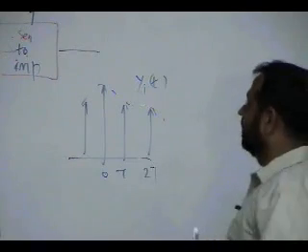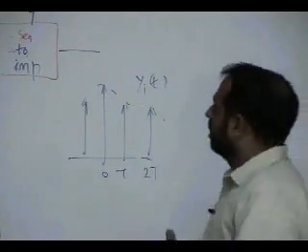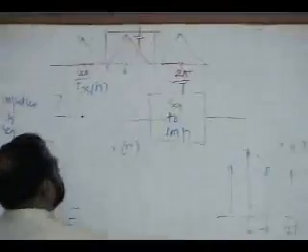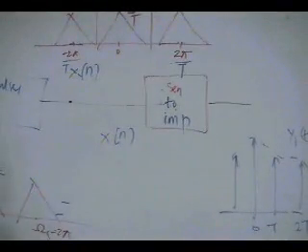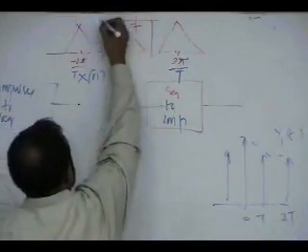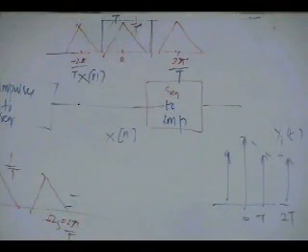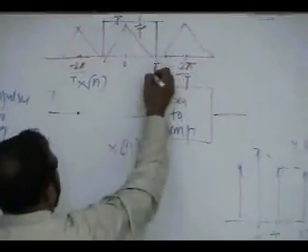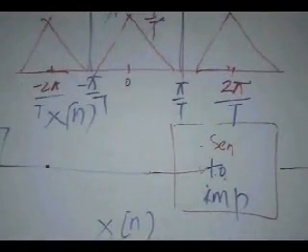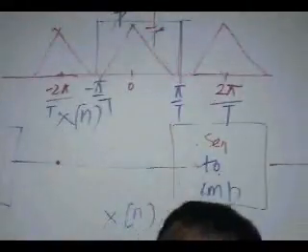Now, okay, this is fine. Then what do you do? Now you have copies of the spectrum. Literally what you do is you put it through a low pass filter. And this is all you do to convert a signal from discrete domain to continuous domain: you pass it through a low pass filter with gain capital T, because T will cancel out with this T, will give you gain 1. And with cutoff frequency always at pi over T and minus pi over T. Okay, always. Half the sampling frequency. Because you want to throw away these redundant spectrum.